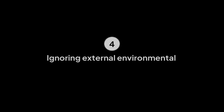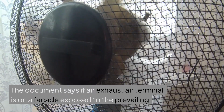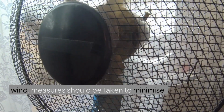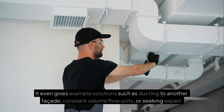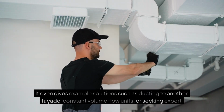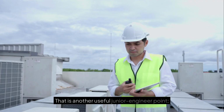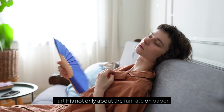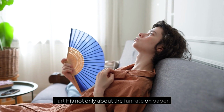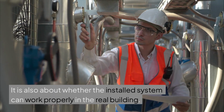Mistake number 4 is ignoring external conditions. The document says if an exhaust air terminal is on a facade exposed to the prevailing wind, measures should be taken to minimize likely wind effects. It even gives example solutions such as ducting to another facade, constant volume flow units, or seeking expert advice. That is another useful junior engineer point. Part F is not only about the fan rate on paper, it is also about whether the installed system can work properly in the real building.